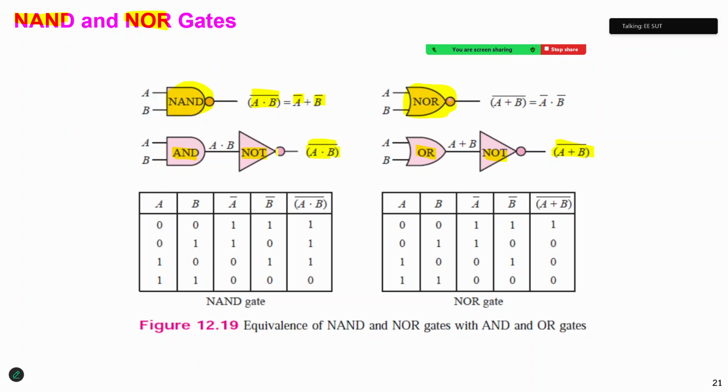So what is the output of NAND logic? If we have the signals A and B, we construct this truth table. A and B is 0, but we invert, we get 1. 0 and 1, A and B is 0, we invert, we get 1, right?